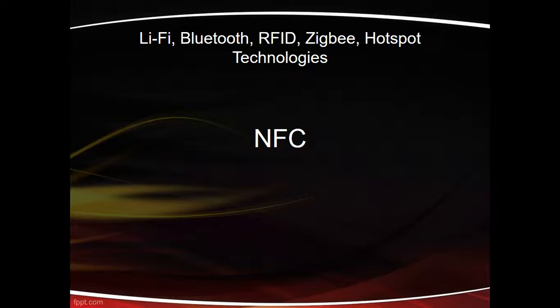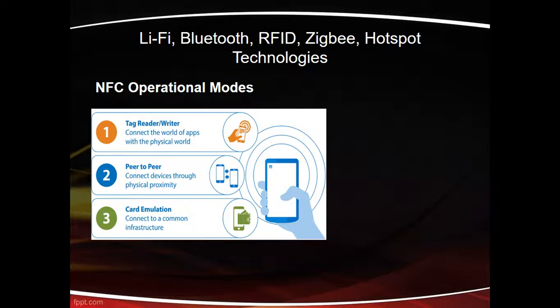As you can see from the operational modes, NFC is used as a tag reader/writer, peer-to-peer, so you can communicate between devices, and you can use card emulation. NFC is also an IEC and ISO standard, and it has features like easy network access and very easy data sharing. Connecting and disconnecting is very easy, giving authority and power to users, and it works everywhere. So those are its features. Applications include credit card payments, e-ticketing and booking, personalized usage, wearables and retail. Some are not used in Sri Lanka, but most of them are. You have seen those things.